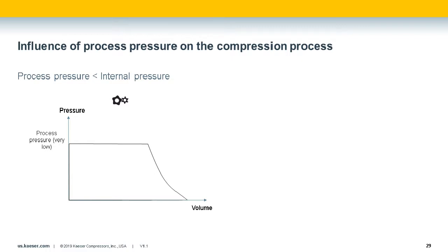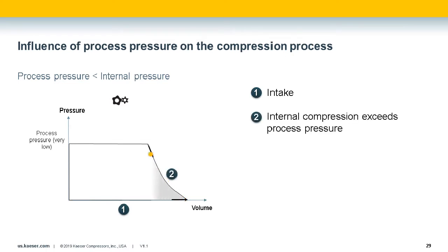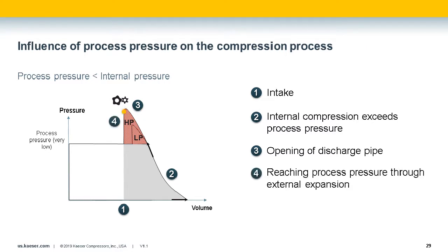And if we hit the next tab a little bit, we'll see the intake for the blower, and then we'll see the compression up to the internal compression. We go by system pressure, and we overshoot with the low and high pressures. To minimize the excessive work or energy associated with the excess compression, screw blowers have evolved in recent years to minimize the overshoot of internal compression. While using the correct rotary screw version, energy savings of 25 to 30% can be realized.